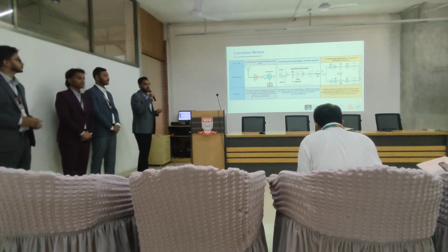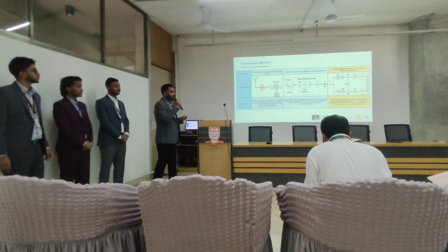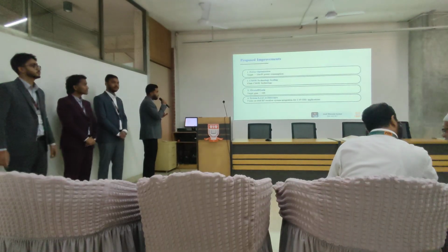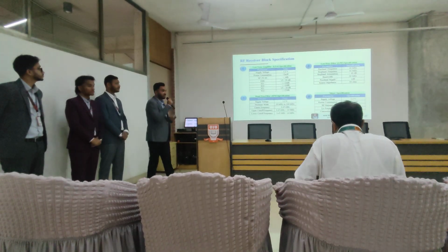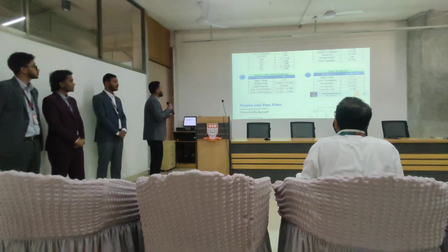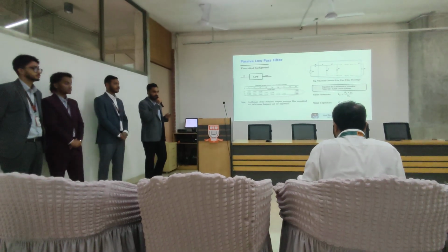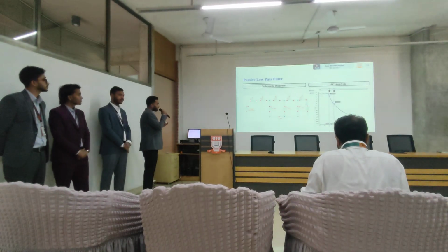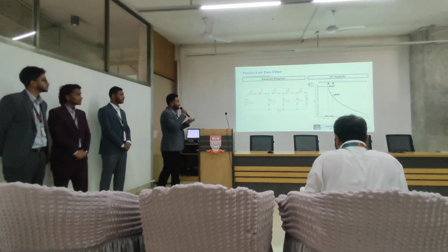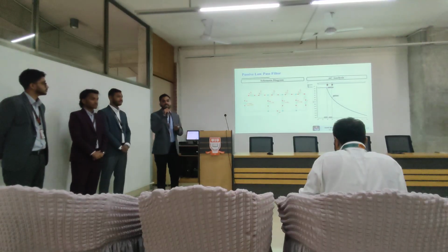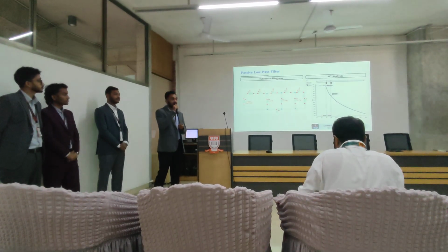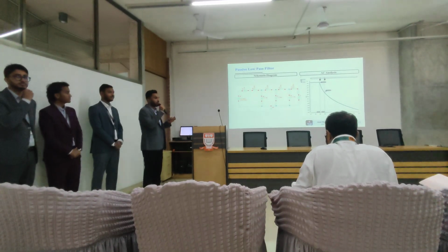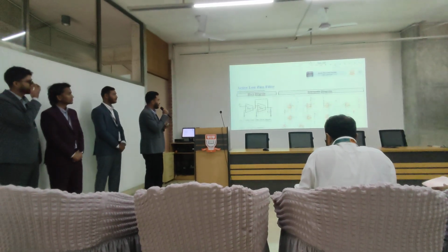Before going to our design procedure, we did some literature review, and on the basis of that literature review and sitting with our vendor, we proposed some improvements, and those are the specifications for our blocks. We designed our RF receiver with a passive low pass filter design, and here is our circuit. Though the analysis ensures all the specifications, there are some limitations in the passive low pass filter design, such as there is no gain control, and since those are discrete components, they need more size. That's why we moved to the active low pass filter design.